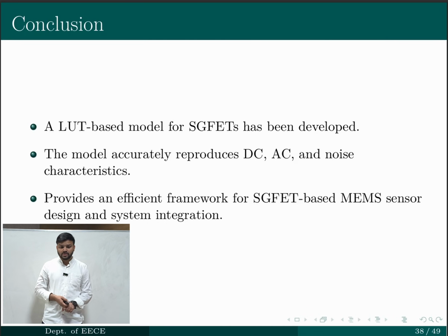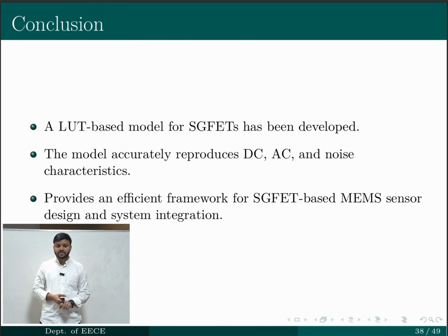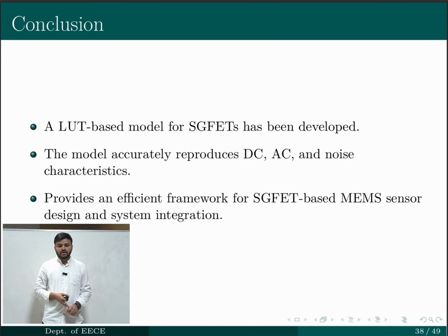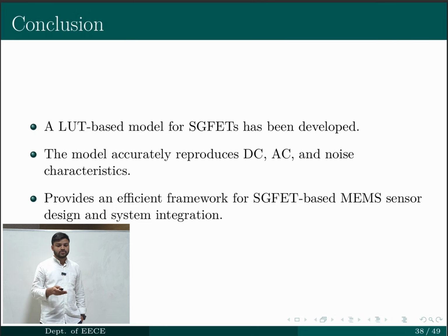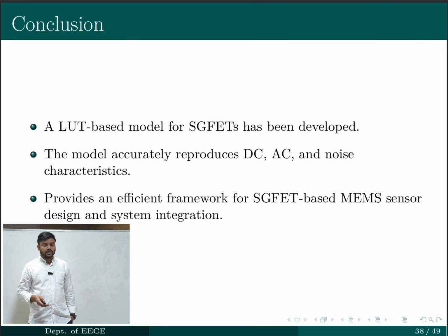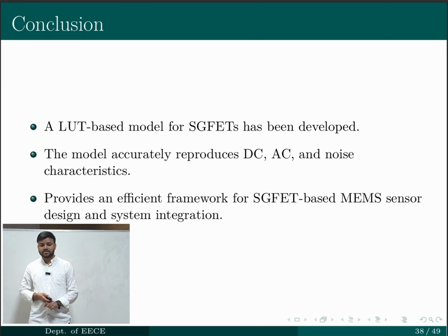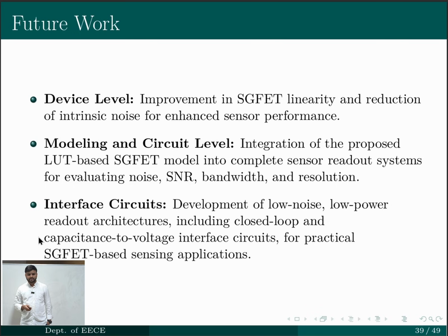Now I am going to conclude. A LUT-based model has been developed for the SGFET, and it is validated: it reproduces the DC, AC and noise characteristics, which provides an efficient framework for SGFET MEMS sensors and for system integration.